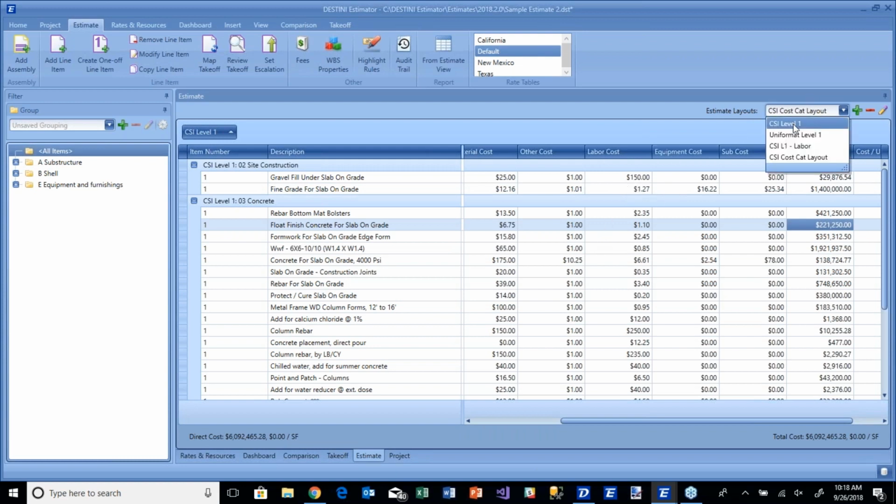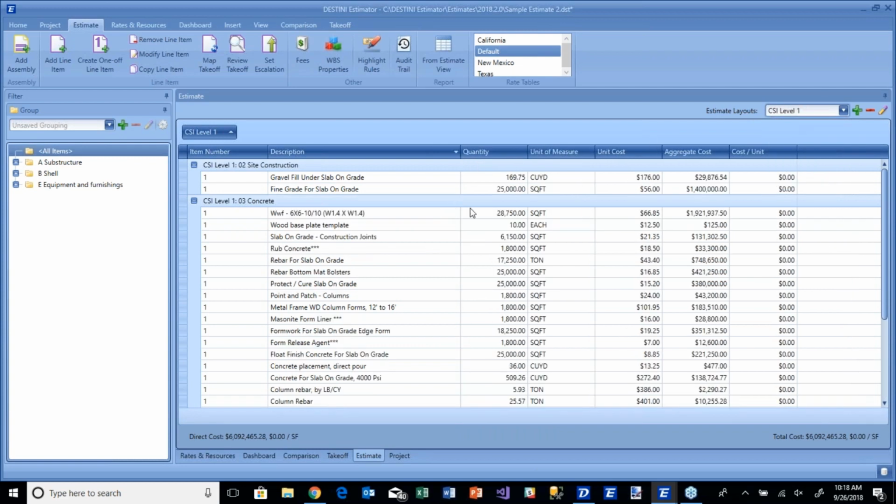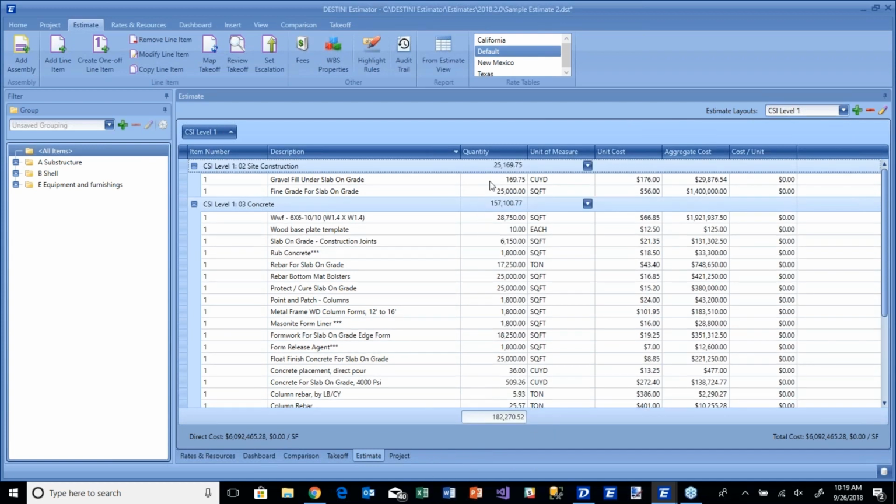All right. Now I'm going to bounce to, actually, stay here for a second. Let's go to a little high-level layout. One of the other pieces that we've offered is the ability to have an overline total for your quantities. Now, you've always been able to do the operation I just did where you can sum up all the values in a column and show that sum here. But what you haven't been able to do is control what that value was. And so right now, the values that are shown aren't really all that valuable for you. So what we've done is the ability to set this value, and we've provided 3 different ways to do that.